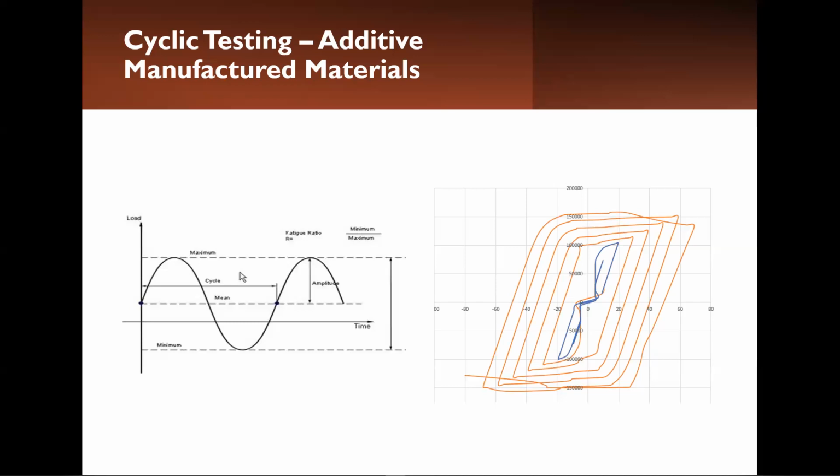And as it has been known that fatigue is lowered in the AM metals, the theory now becomes: does this compressive or tensile residual stress from the surface effect of the thin film coat help this fatigue process? And does this change the kinematic hardening effect at all in the fatigue test?